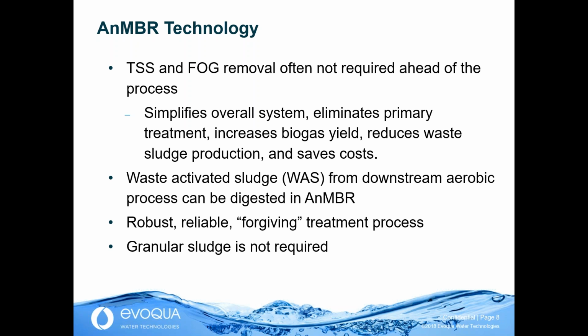Another benefit of the anaerobic MBR, similar to other anaerobic technologies, is that waste-activated sludge from downstream aerobic processes can be sent to the anaerobic MBR for digestion.